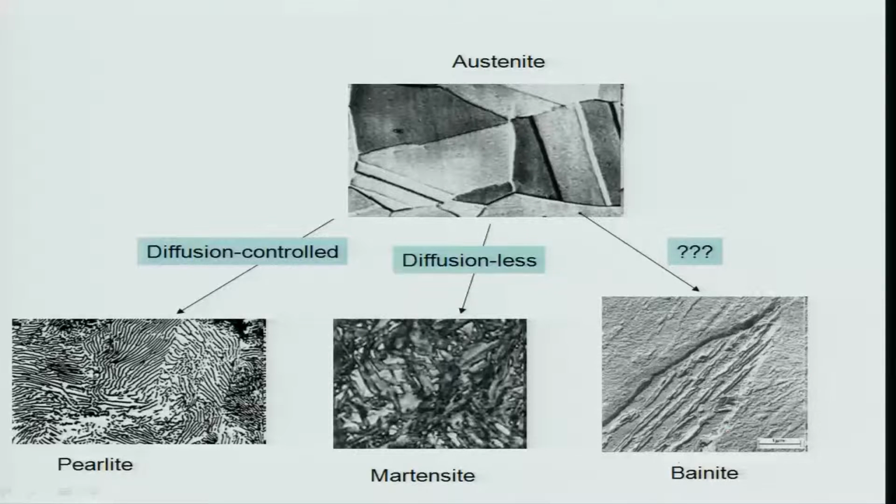So, this is the bainite, typical bainite you see here. It is like a feathery bainite, just like a leaf, and within that leaf you have cementite and alpha iron. The cementites are the red color thing, and this one is alpha. So, this is like a tree bunch, sorry, tree leaves, in which these are actually the cementite, and the remaining dotted parts are actually alpha. So, this is one such morphology which is observed.